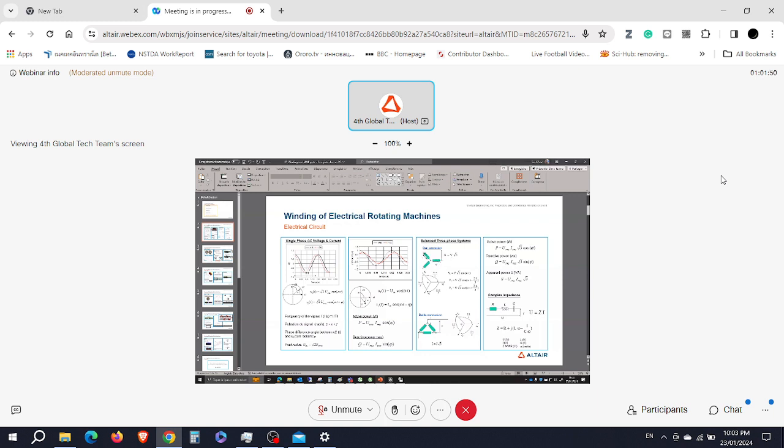That's why we need to go back to the phase-to-neutral voltage. So here the link between the line current and the phase current is done by this same ratio or factor, root square of 3. For this three-phase system, as I told you, the active power is 3 times this one, and the same thing for the reactive power and apparent power.